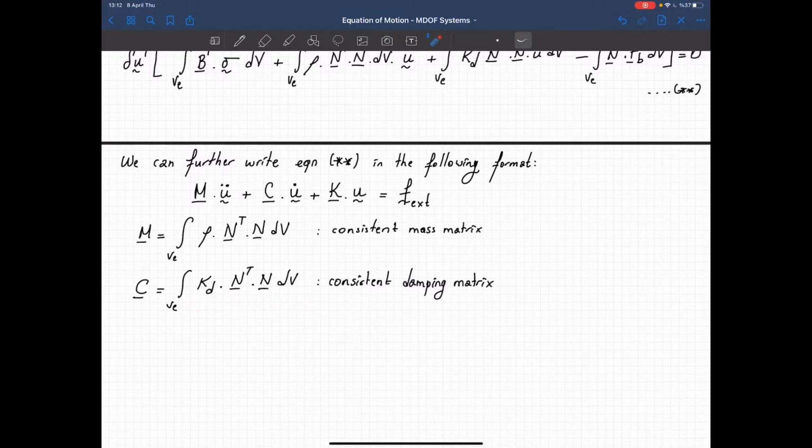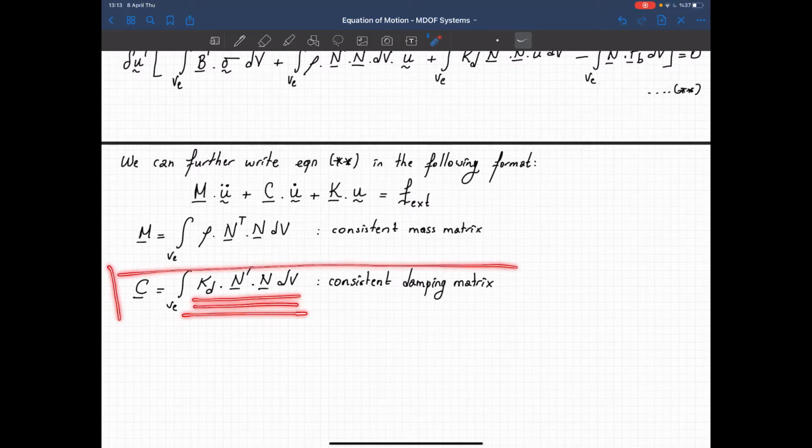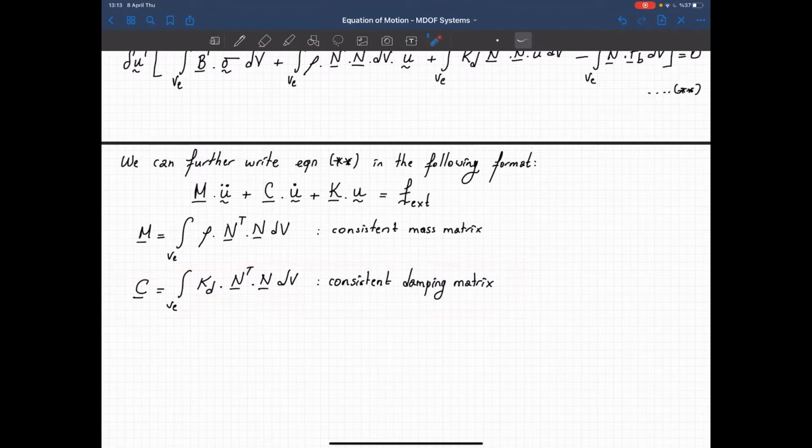Okay, this approach could be good for Newtonian fluids, but in solid mechanics, this type of damping is not very effective. We have other types of damping. We call them internal and structural damping, which we will talk about. So that's why in solid mechanics, we don't use the damping formulation in the following format. So let's put that as a note. This is for Newtonian fluids.